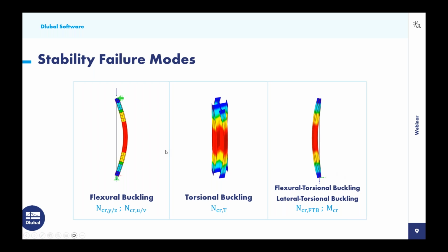And the problem is that 6 degrees of freedom can only consider flexural buckling. Now, we can go ahead and say, well, if we are designing according to AISC or CSA, of course, the codes have analytical equations that are going to design for these additional stability failure modes. But this is in the design process. What I'm talking about specifically is with the static analysis as well as the structural stability. So how do we consider these additional failure modes?